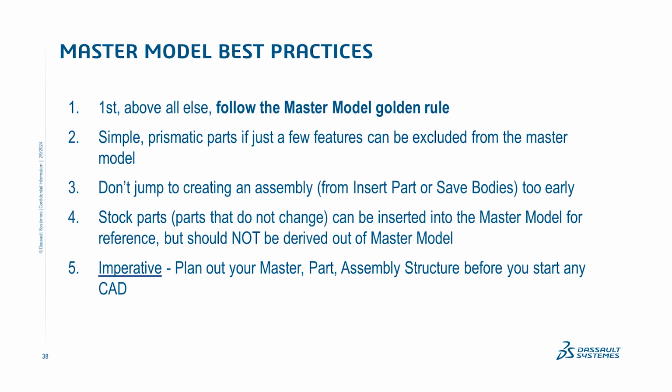I also find that there is some ambiguity on what to do, even if it is features shared between multiple parts, if that part is prismatic and very simple, maybe it could be created with a few features. Maybe consider it not being included in the master model. Mechanisms and understructure that's very simple in its geometry, with very few features, oftentimes I won't include in the master model. I maybe will put a reference sketch to it, but I won't be building it in the master.